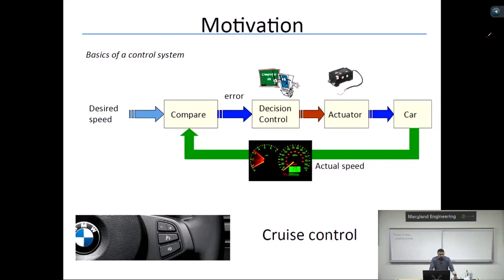The purpose of the controller is to ensure that you have the desired behavior. It tries to drive that error to zero, and a control signal is generated that, when applied to the actual system, which is the car, would make the error go to zero. Control signals are applied to systems through actuators. An actuator is basically a component through which the control system interacts with its environment. For example, in your car, there is something called the cruise control actuator.